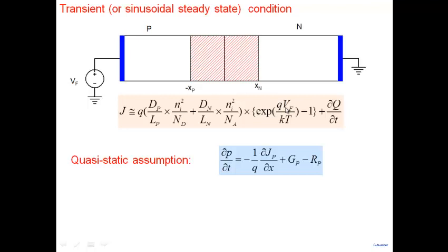What we are saying is that as long as a certain voltage is there across a PN junction, the current will obey this particular equation, right? The conduction current. But if you go back and look into the derivation, the current has been obtained through solution of the continuity equation. And when you solve the continuity equation, remember, you get excess hole density and excess electron density, and from there you get this particular value of current.